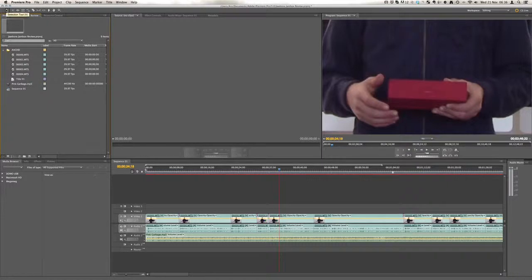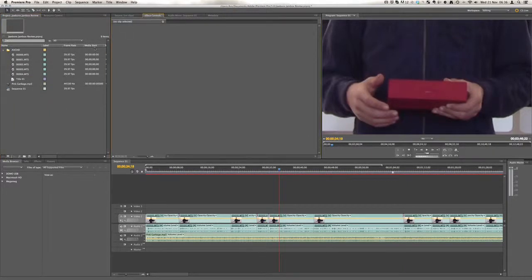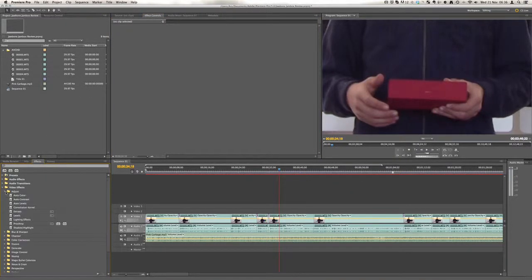So for example, here is the selection tool, and you can press V on your keyboard. There's a keyboard shortcut for every single one of the tools, which are very handy to know. If you just hover over its icon, you'll see it. The V, or the selection tool, just allows you to select clips and move them around. It's also best for finding effects, so you can come and find an effect, say video effect, adjust if you wanted more contrast. You can just easily drag that on.